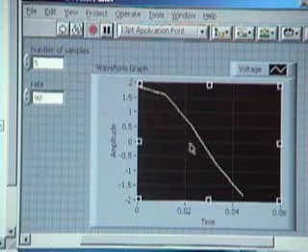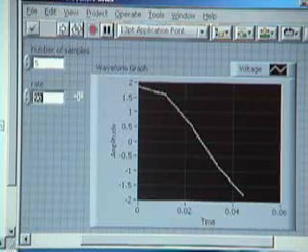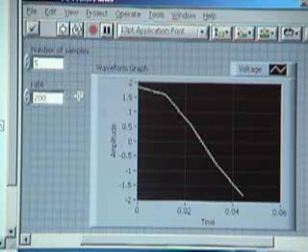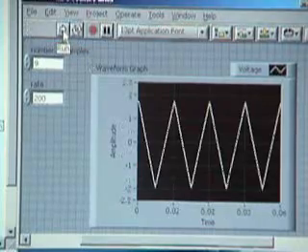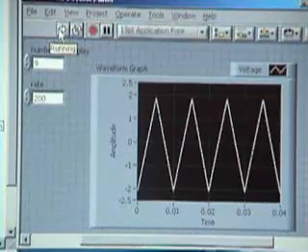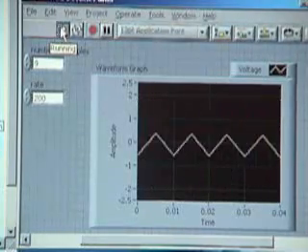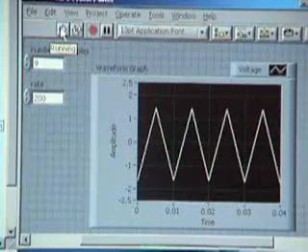You can see that this looks nothing like 4 periods of a sine wave, because we're sampling at a very low frequency. You can try sampling at the Nyquist frequency, which is twice the maximum input frequency, so it's 200 Hertz. And to get 4 periods of the input frequency, we need to take 9 samples. So every time I click the Run button, it's starting the sample at a different point in the waveform, so the amplitude changes. Although we're still getting the frequency content, we're not getting the amplitude content.